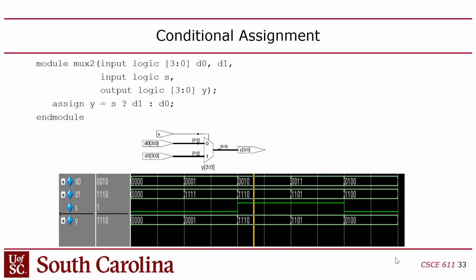Okay, another thing that's very common in Verilog is the ternary operator. The ternary operator is available in Java and C. I don't know if you can do this in Python, but basically the idea is you have a condition followed by a question mark, and then whatever comes after that question mark is what the whole expression evaluates to if the condition was true, and then you have a colon, and then you have the value it evaluates to if the condition was false. This is available in C and Java, but hardly anyone ever uses it. It's very obscure and rare in those languages.